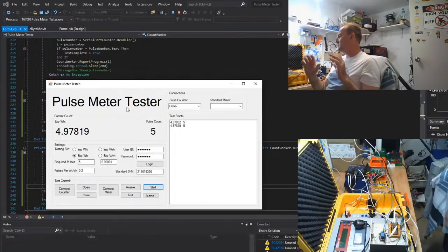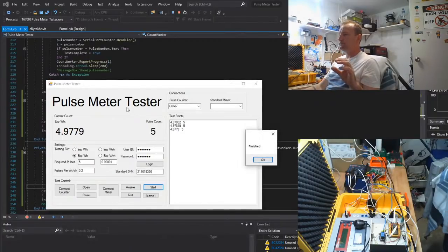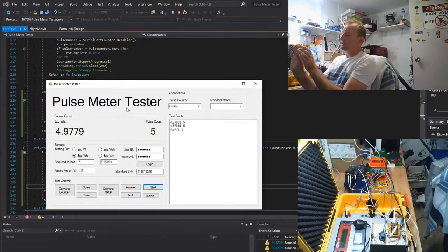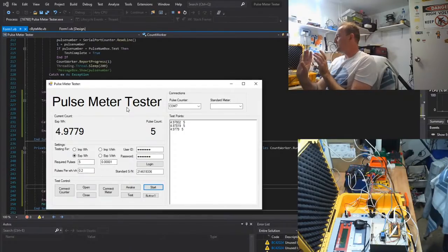So what happens with AC is, depending on what type of load it is, the current will start to lead or lag the voltage, and that actually affects how much power you're actually consuming, because of the reactive component, the bit that's left out, you don't use it.